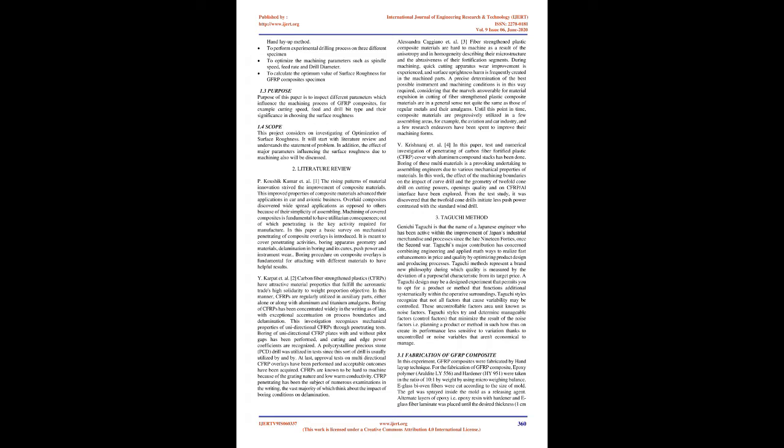Drilling is the most often used machining method in industries to assemble mechanical parts. Drilling of GFRP leads to drawbacks like delamination at the entrance and exit, fibre pullout, and poor surface finish. Considering the productivity and cost of drilling, optimization of process parameters is very important to get higher material removal rate.